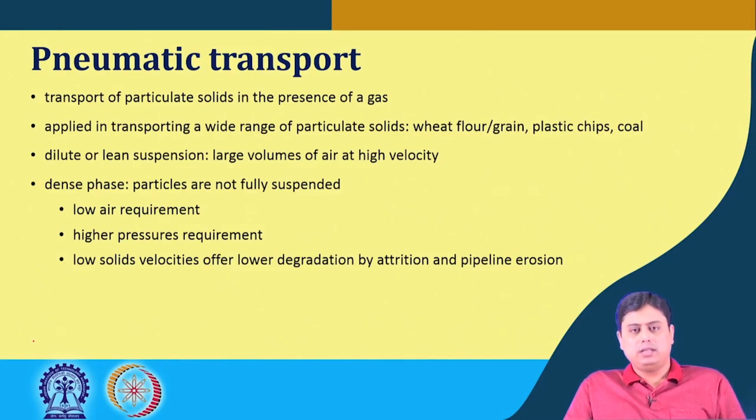Now since here the velocity of the air that induces the movement of the particles is lower, it offers lower degradation of the pipeline network by attrition or erosion. So these are the benefits we have in dense phase transport, despite the particles not being fully suspended.